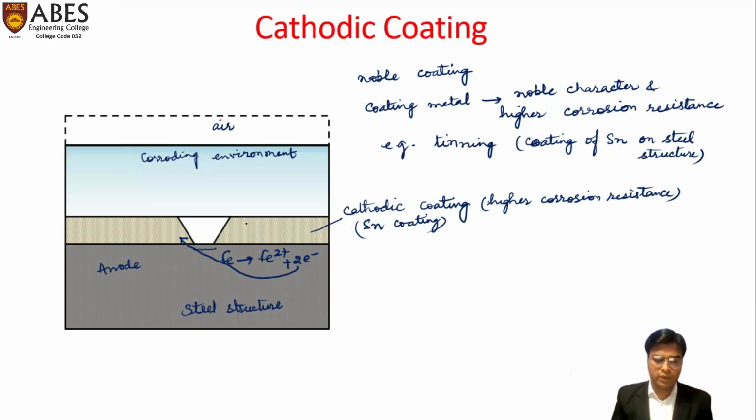So this kind of coating will work only till this coating is intact, free from any discontinuity or any kind of pore. Otherwise, it will lead to intense local corrosion or pitting corrosion.